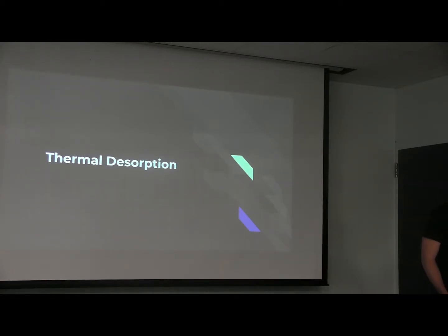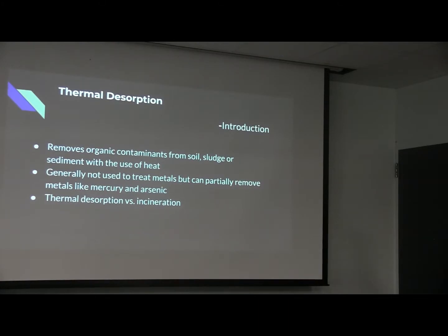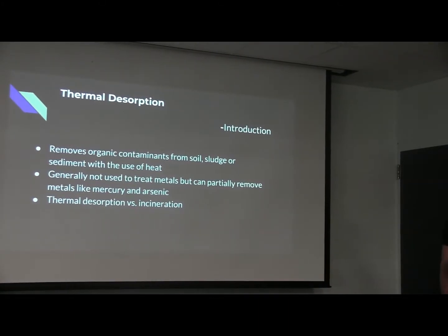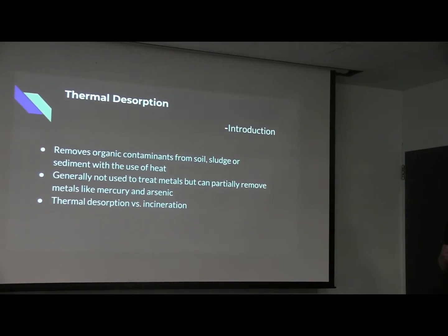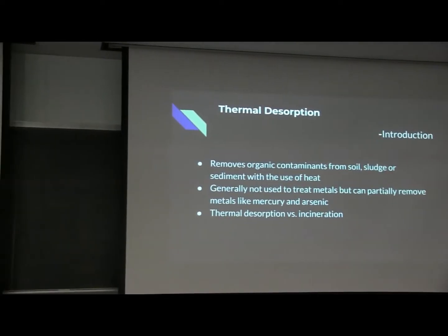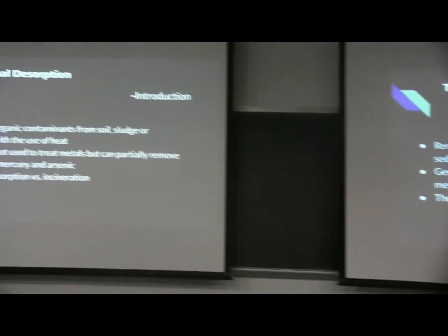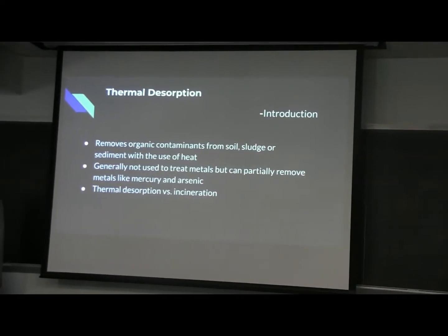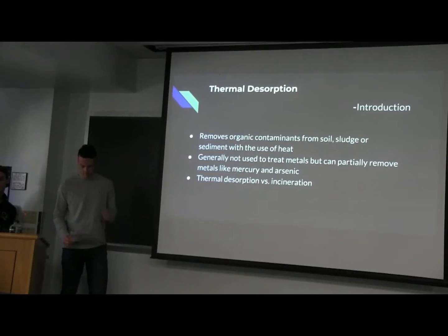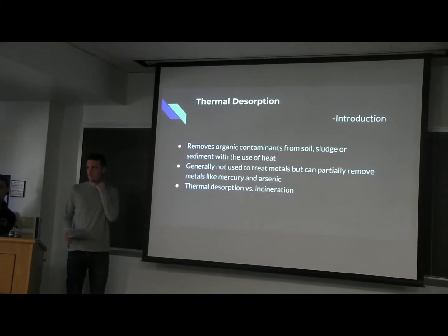So thermal desorption removes organic contaminants from soil, sludge, and sediment with the use of heat. This method is different than incineration because this method requires heat to physically separate the contaminants instead of actually destroying them, which is what Nick talked about earlier.